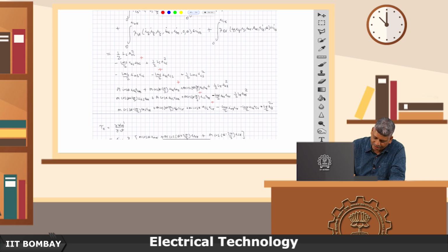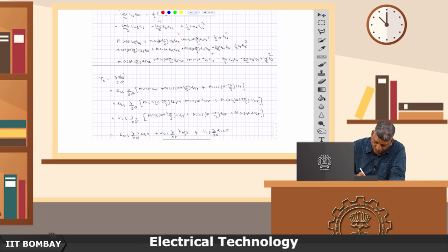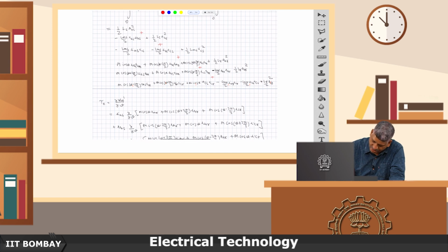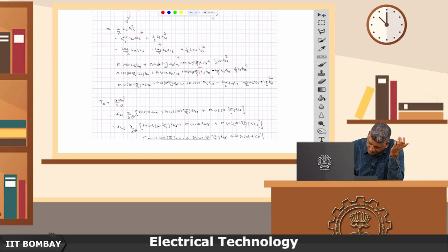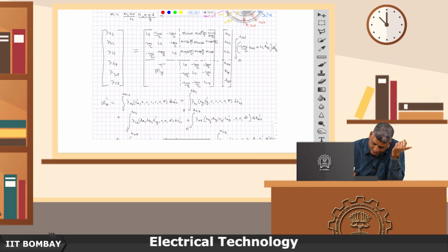the flux linkage. So all the 6 currents will now come into the picture. So I have 1, 2, 3, 4, 5, 6, I have all the 6 terms here. Again, the first 3 terms are very similar, the last 3 terms are very similar to the corresponding C phase flux linkage term we had derived earlier for the stator, except that the S is replaced by R. The only really interesting terms which need explanation are these, but you can explain them from this column here.